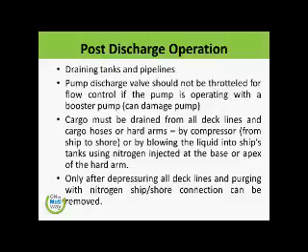And of course, once we finish the discharging and when we finish the stripping, what we will do is drain the lines and purge the lines with nitrogen. So at the end of the day, we bring the lines to the ambient temperature, and we will also fill the lines with nitrogen. So there is no hydrocarbon gas in these lines.